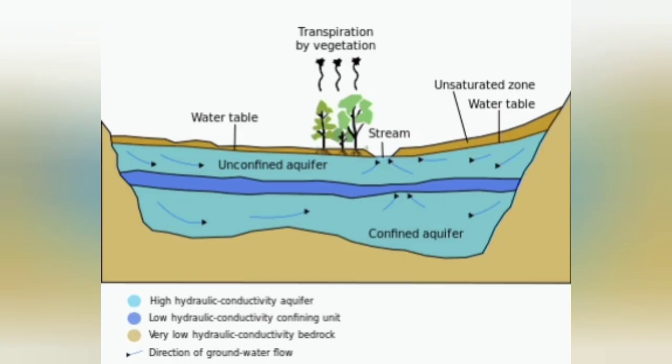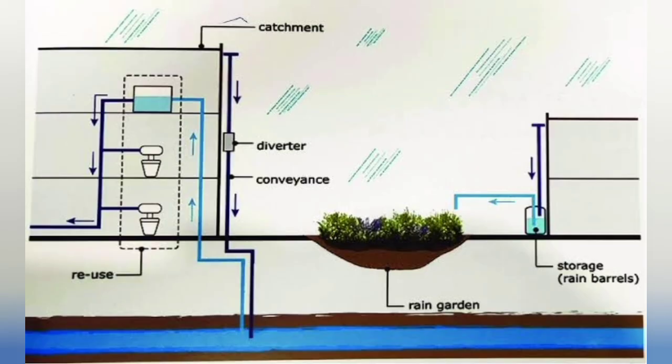Nevertheless, the application of geophysical methods is to bring out a comparative picture of the subsurface lithoenvironment, surface manifestation of such structures, and correlate them with the hydrogeological setting. Besides defining the subsurface structure and lithology, it can identify the brackish or fresh groundwater interface, contaminated zones and areas prone to seawater intrusion.